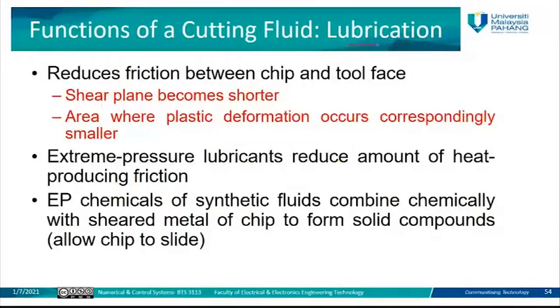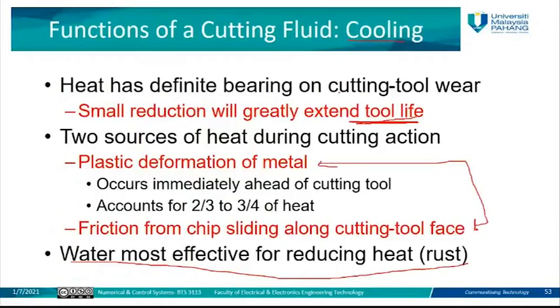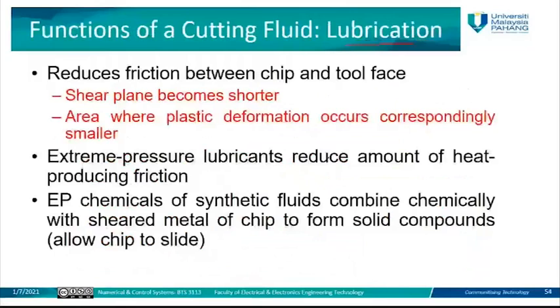For the lubrication here, because we said the primary functions are cooling and lubrication. So for the cooling, this is the benefit from using cutting fluid for cooling, and here is the benefit from using cutting fluid for lubrication. It will reduce the friction between the chip and tool. So the shear plane becomes shorter. Also, the area where the plastic deformation occurs is correspondingly smaller.